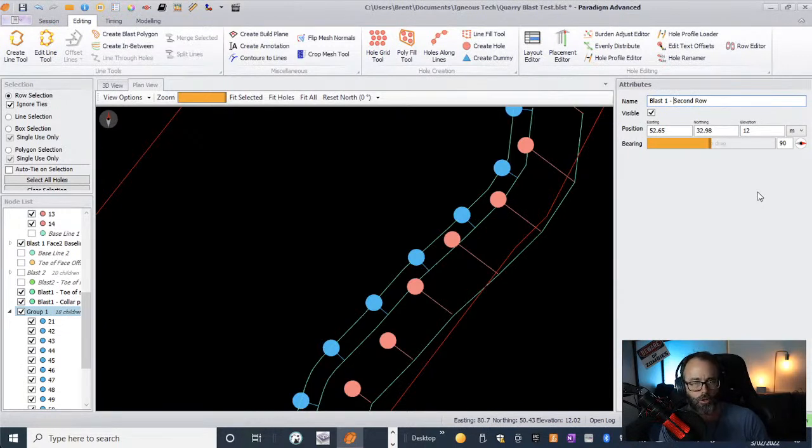So like in Vulcan blasting design module, I give them a color, and then you can see there's a little F icon that you can pin to the panel, and you can find by color. I love find by color because people think in colors, and it makes it a lot easier. Or you can group them. There's always many ways to do the same thing,